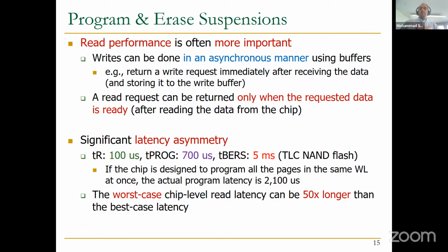And since the program latency for each page is around 700 microseconds, you need to spend 2100 microseconds to program the whole 3 pages. So the problem here is that the worst-case chip-level read latency can be 50 times longer than the base case latency.